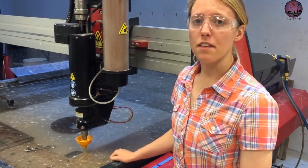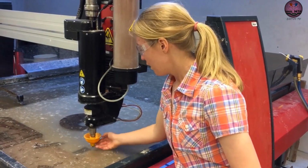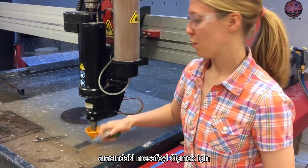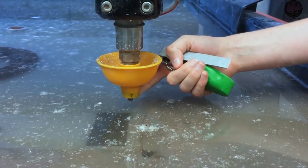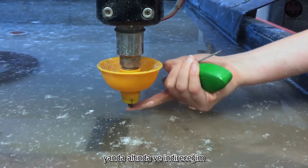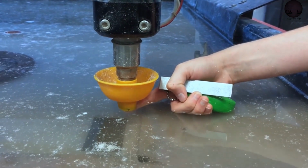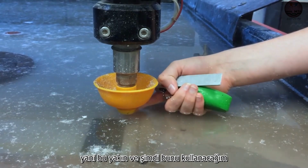So the next step is to set the Z height, which is the height above the top of your material. So you want to get it very close, but not touching your piece. And in order to get that distance, we have a tool you can use to measure the distance between the nozzle and the piece. So, in order to get the distance, I'll use my finger gently resting on the side of the nozzle, not underneath, on the side, and I'll lower the nozzle using the 1 key until my finger is touching it. You want to be about 1 finger width above. There we go. So that's close.